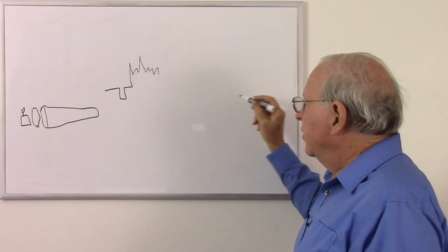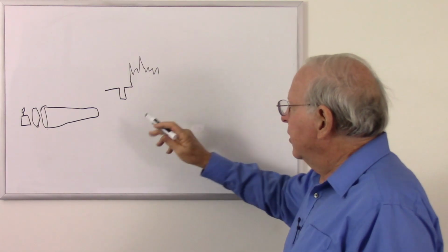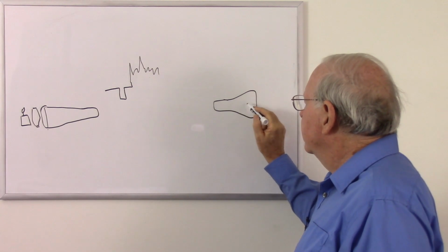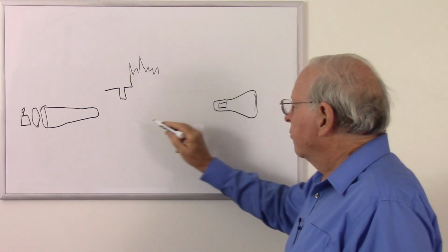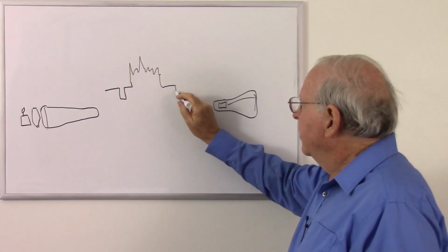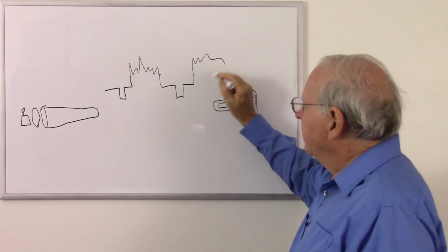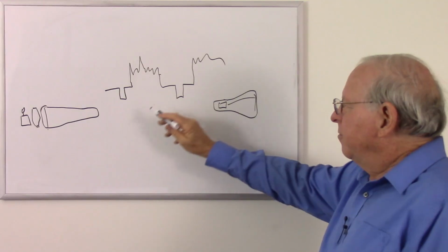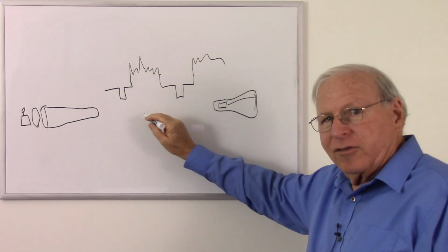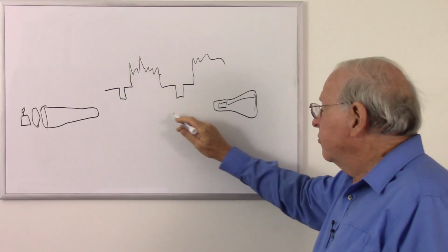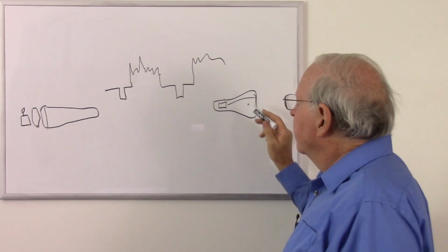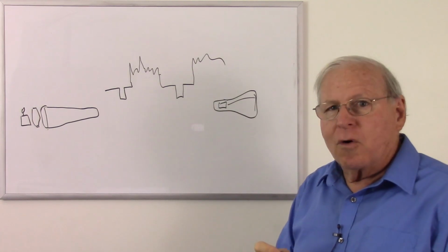That told the oscillators on the other side how to synchronize to keep our picture tube, which is recreating this image on a phosphor screen using an electron gun, painting the screen and taking this signal line by line. So here's one line, scans across, makes brighter and darker spots, synchronizes the oscillators, goes down a little bit, scans another line, giving us light and dark spots to paint the image that this camera tube is picking up over here. So now what we need to do is figure out a way to record this.